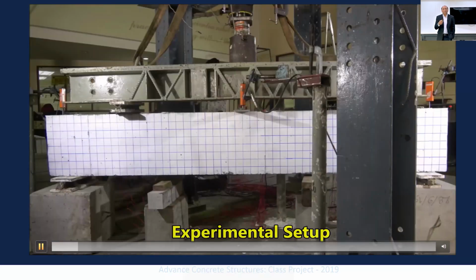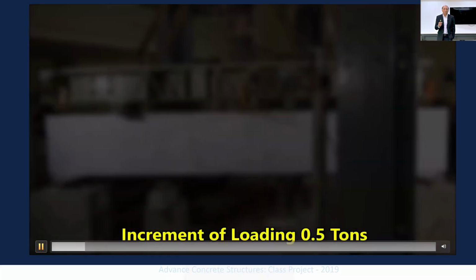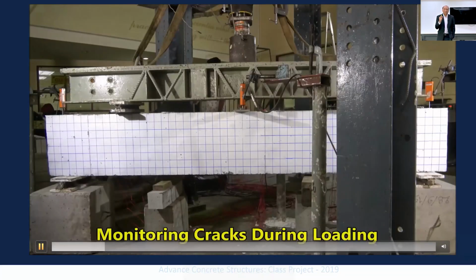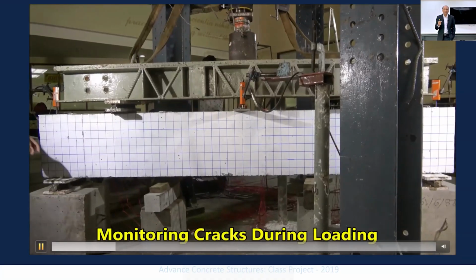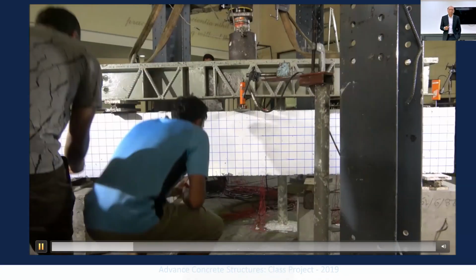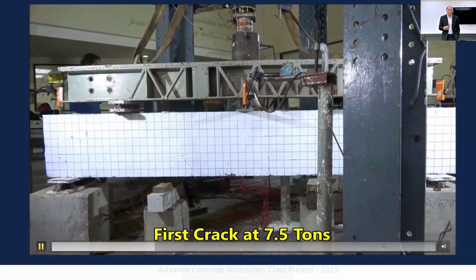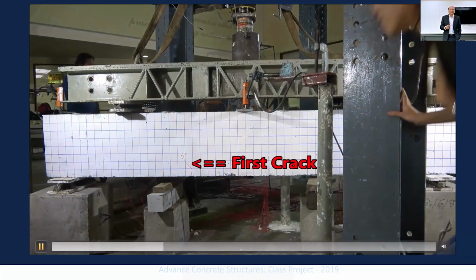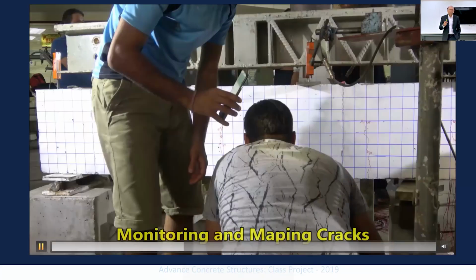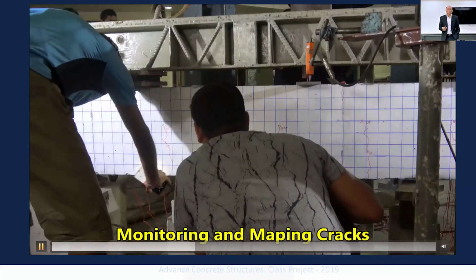When you test the beam, you can observe the deformation, the cracks, and the strain. You put strain gauges everywhere, start measuring everything, and notice what's happening. You can observe the first crack, note down the load at that first crack, and continue to observe the behavior of the beam until it completely breaks down.